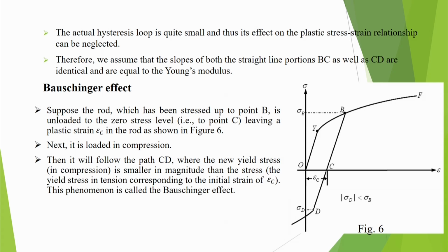You expected that it will start at some stress, say 200 megapascal, but maybe it will start at 195 megapascal. So, this is due to the Bauschinger effect.